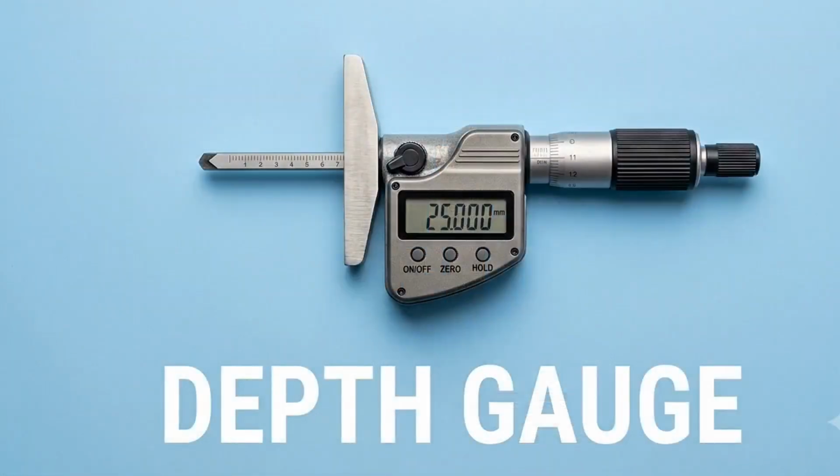A depth gauge measures the depth of holes, slots, grooves, and recesses. Construction workers and machinists use it to verify that drilled holes meet the required specifications. Accurate depth measurements are important when installing anchors, bolts, and pipe fittings to ensure proper performance.